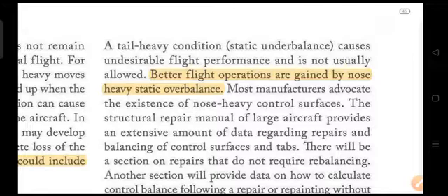Better flight operations are gained by nose heavy static overbalance. You need to have a bit of nose heavy condition. Nose heavy condition will help you to come down easily. It will not allow the aircraft, whenever you increase the speed, to immediately change its altitude and go up.